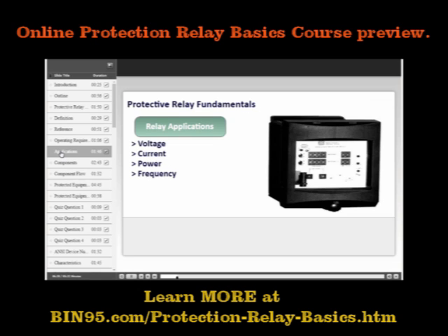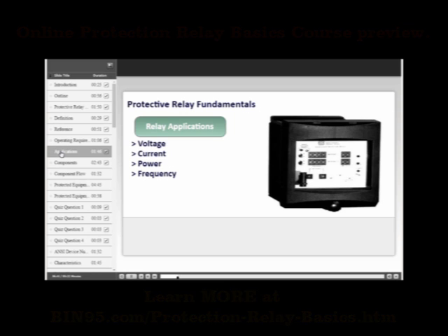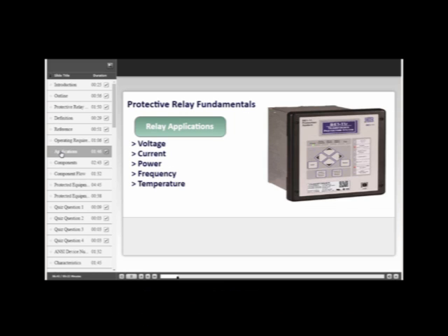Controlling frequency is a major concern for systems. Costly damage to equipment can result from an over or under frequency condition. Device number 81O for over and 81U for under are the proper selection as seen here. The Basler BE1-11T relay helps.